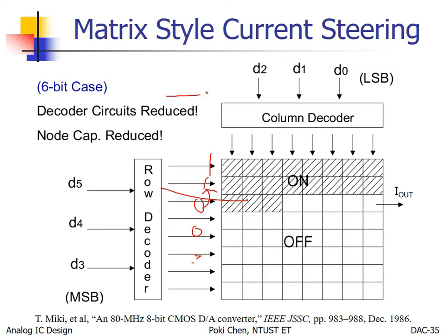If I'm 0, I get this, and then you need an AND gate, for your upper neighbor and myself. See? If I am 0, I will get 1 because here is the NOT gate, and my upper neighbor needs to be 1. Then, bingo. I am the first 0.